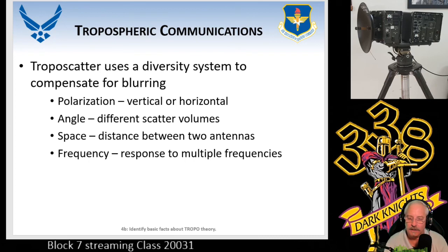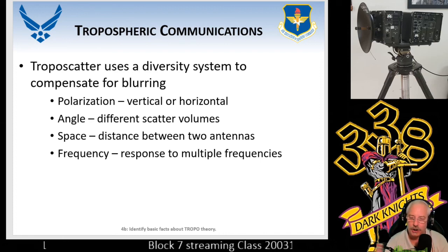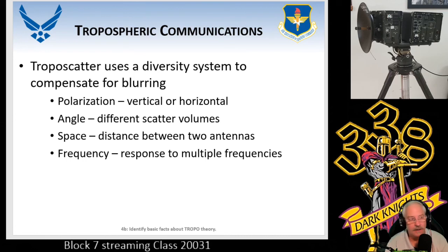Because if you take a look at your cut sheets and you put site 1 versus site 2 side by side, you will find out that your transmit frequency is the same as the distant receive frequency, and their transmit frequency is your receive frequency. Your antenna waveguides will be opposite in polarity, and that's so you don't interfere with each other. So not only are you 200 megahertz apart as a minimum, you also have to be vertical versus horizontal.